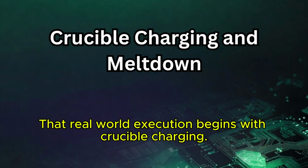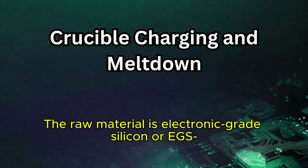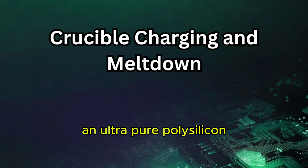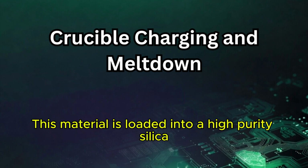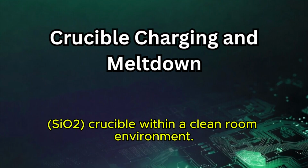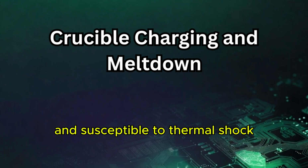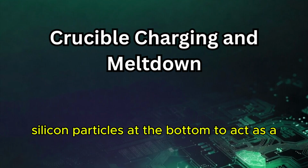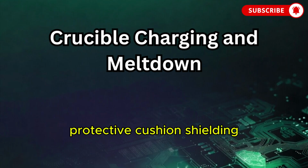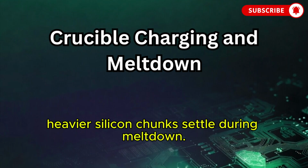That real-world execution begins with crucible charging. The raw material is electronic-grade silicon, or EGS, an ultra-pure polysilicon with impurity levels below 1 part per billion. This material is loaded into a high-purity silica, or SiO2, crucible within a cleanroom environment. Because silica is highly brittle and susceptible to thermal shock, structural packing is critical. Technicians place smaller silicon particles at the bottom to act as a protective cushion, shielding the quartz from being gouged or cracked when the larger, heavier silicon chunks settle during meltdown.